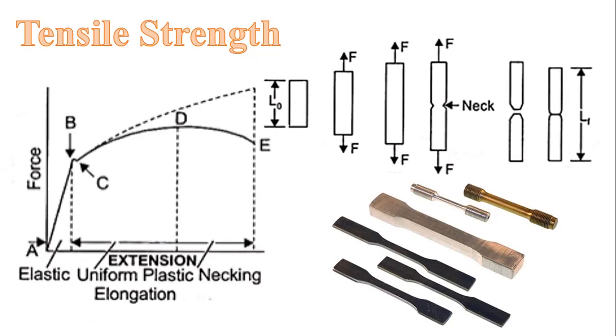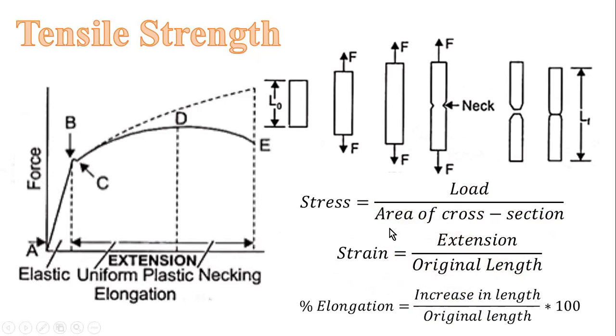In general, values of load and extension are of limited use since they apply to one particular size of specimen, and it is more usual to plot the stress versus strain instead of force versus extension. So you will need to calculate the stress to obtain a plot like this, to plot stress against strain.